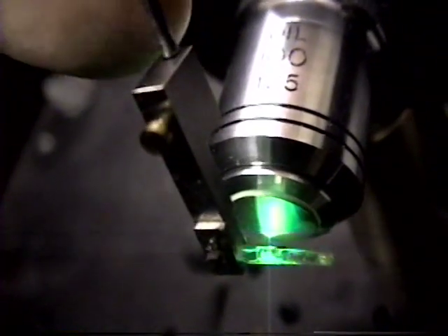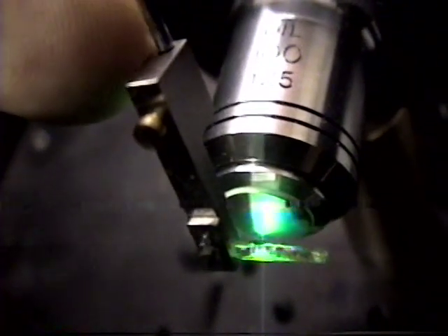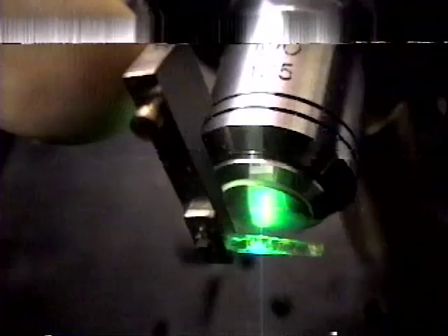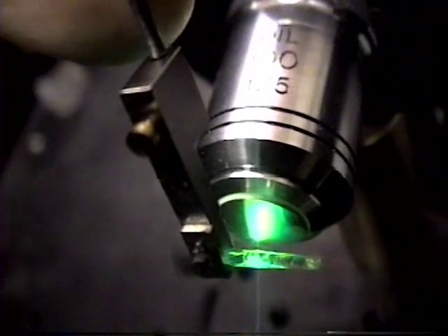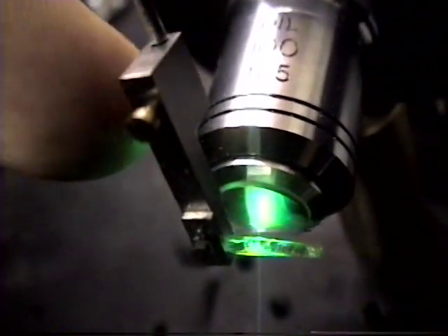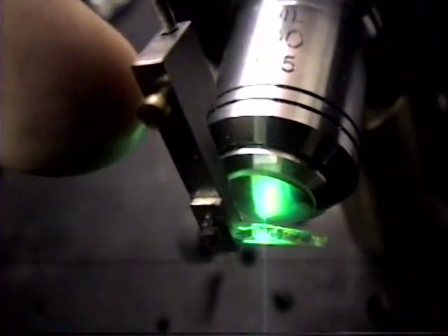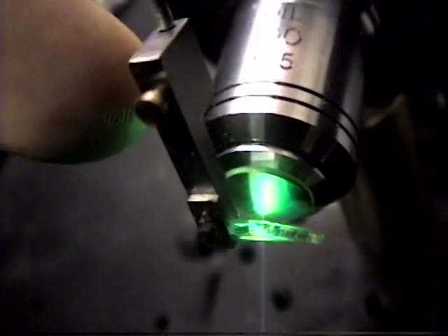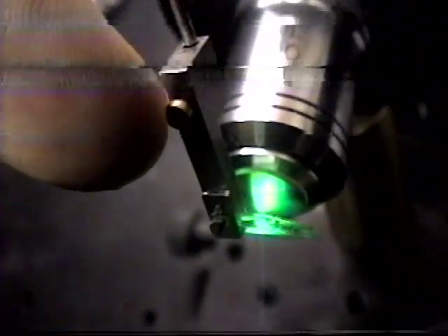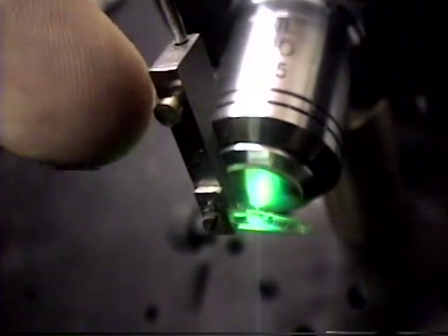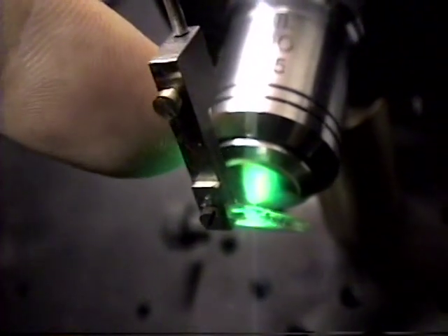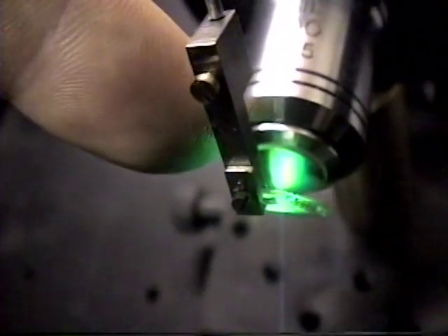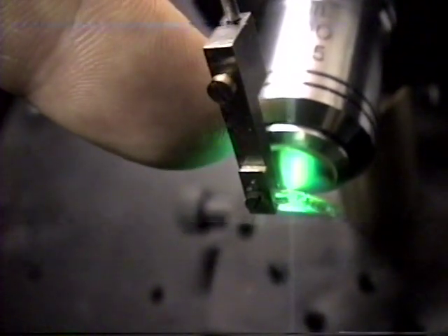One's serving as a jacket to the other one, in sort of almost a telescope arrangement, but it's not actually getting telescoped. The smaller size tube is just the correct diameter to fit over the cladded fiber, and that smaller size tube is getting clamped in place by this brass screw here, and it's holding the bare fiber that's just been cleaved, just the bare ended fiber.